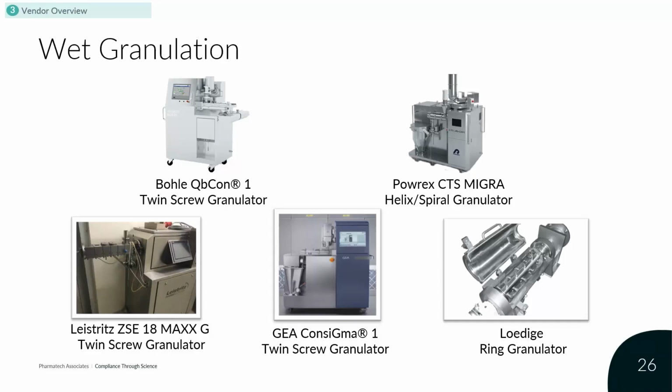What about the temperature control? And what is the flexibility on the length of the process itself? So can I really use it just for wet granulation? And I think this is what you can see here in those pictures. These machines are really tailor-made for wet granulation purposes. And so these are questions you have to go through to say, okay, what is the best fitting equipment for my purpose?